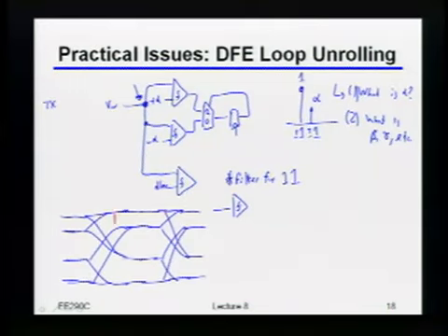If I put my threshold level up over here, then indeed I could find all of the other taps simply by using this as my reference level. Because remember, it's a linear system, so the errors around this reference level are the same as the errors around this reference level. In other words, I can choose any one of these 4 reference levels, and as long as I filter my data to find that one reference level, and then I look for all of the rest of the taps around that reference level, then indeed it should work. Okay? So that actually answers how you do number 2.